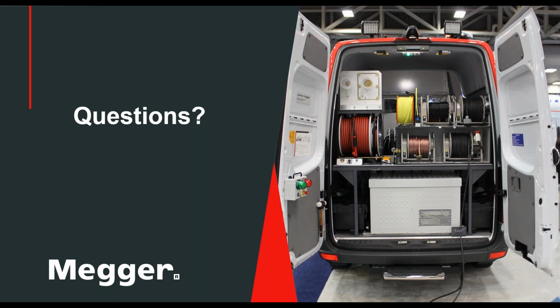So during testing, must both cable ends be connected to the equipment or not? Say, for example, a transformer is connected to a motor through the cable. Well, whenever you test, you can only test from one end of the cable. When you do fault locating or cable testing, you have one end connected to your test equipment, and the other end of the cable must be open, must be isolated. It cannot be connected.